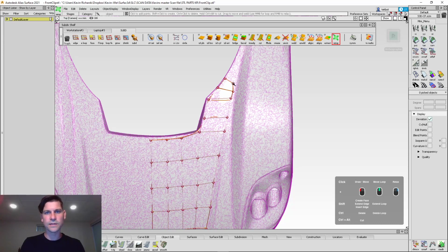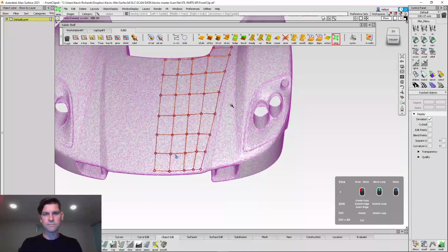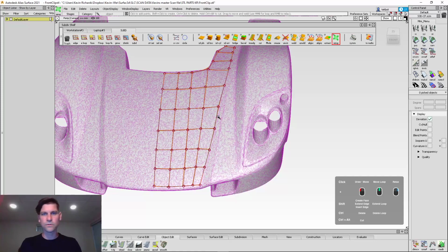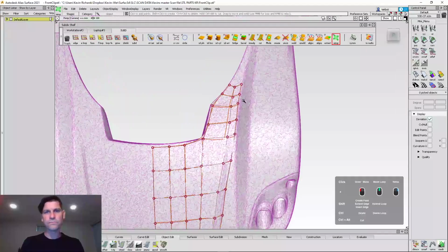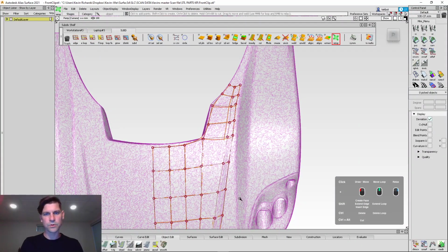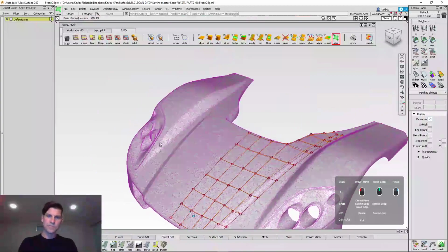We'll start walking this one around, and we would probably want to give these just a little bit more room as it came off of this piece here, because all the points, control vertices, CVs, are going to flow along here. And that's looking pretty sweet. Then I'm just going to hold shift, middle mouse button, drag this out, and we probably won't complete the whole car, but I'll show you some ways that I approach this, just to get going.